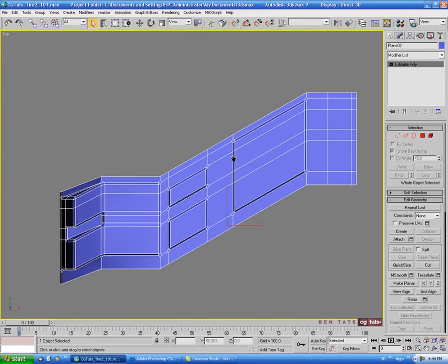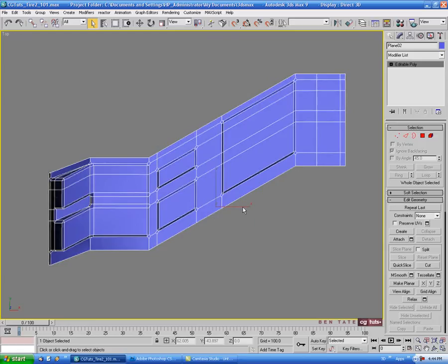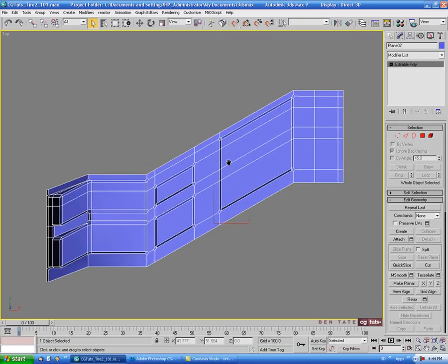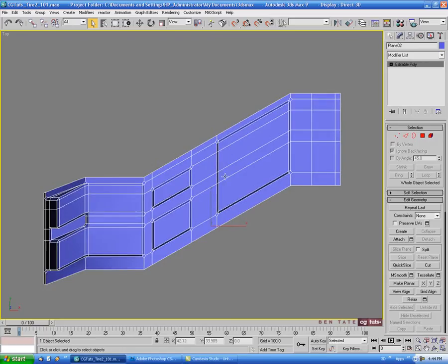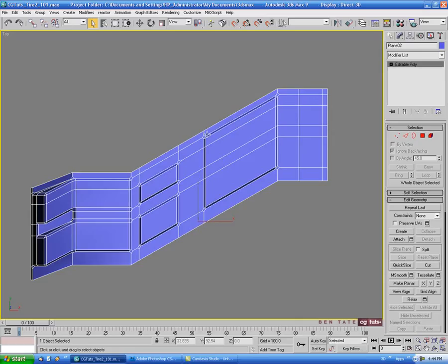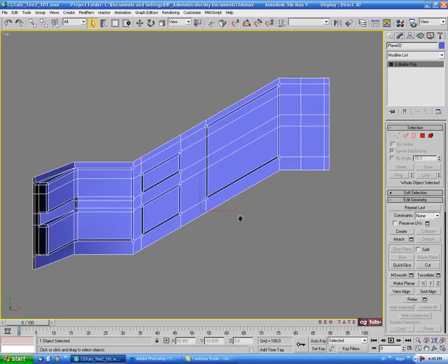And one thing to note when you're modeling a tread pattern like this is you want to make sure that if you have a vert on this side, you have a corresponding one on the opposite outside edge. Okay, so that this is pretty much a tileable piece. If it's not tileable, you'll never be able to clone it and weld it into a finished strip. Okay, so always make sure that you have corresponding verts on both sides, and that the lines are pretty much parallel, so they'll fit together properly when you make your clones. Alright, so that's something that's essential that you need to keep in mind.